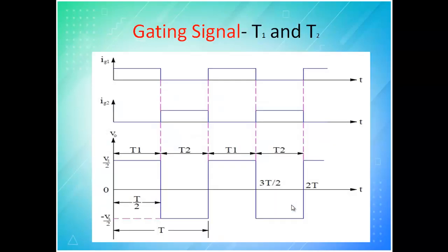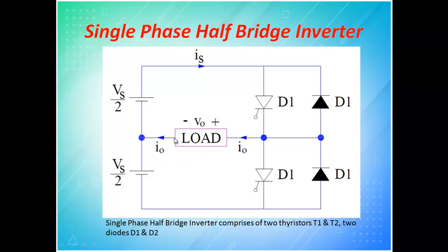Okay, so you can see here, assume this is an inductive load. From this supply, through this semiconductor, I was giving to this. Once this switch is off, this inductor has stored some amount of charge that will try to flow across this diode and come back to the source. So it is freewheeling. I am again supplying something to my source. This will take place during the negative half cycle, or let us assume this thyristor is turned on between 0 to 10 milliseconds. This diode will work for 10 to 20 milliseconds.